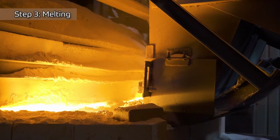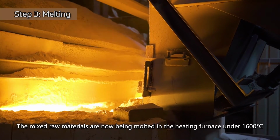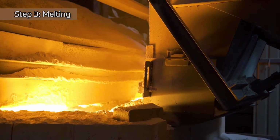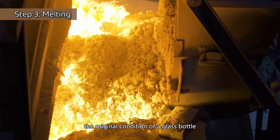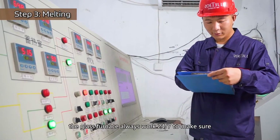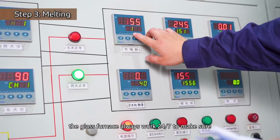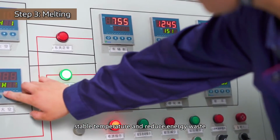Step 3. Melting. The mixed raw materials are now melted in the heating furnace at 1600 degrees. In this step, we get melted glass called gob, the original condition of a glass bottle. In a glass bottle factory, the glass furnace always works 24 hours a day, 7 days a week to make sure of a stable temperature and reduce energy waste.